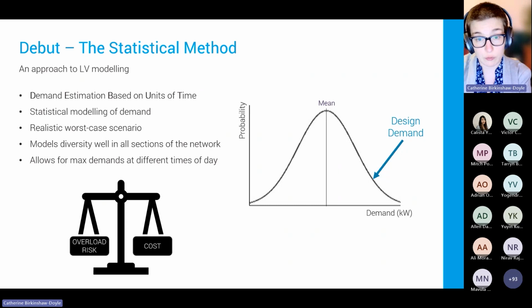So on a cable that's got one customer on it, on the service cable, you've got a one customer level of diversity. Further up the network, with many customers, you're approaching the far end of the ADMD per customer curve, and you're getting this lower equivalent per customer.